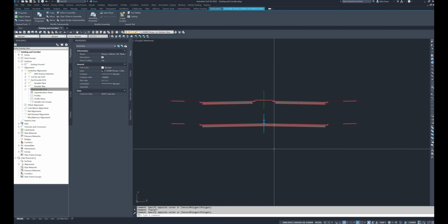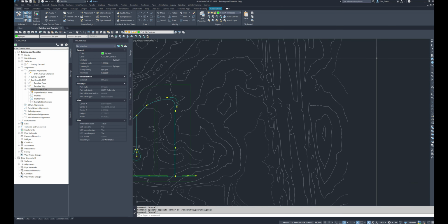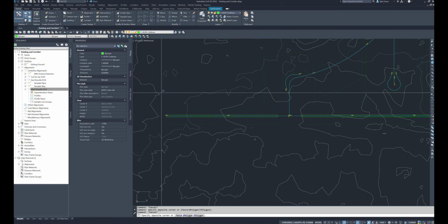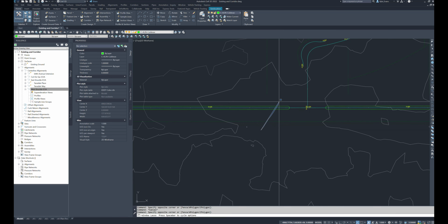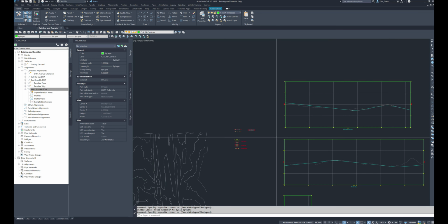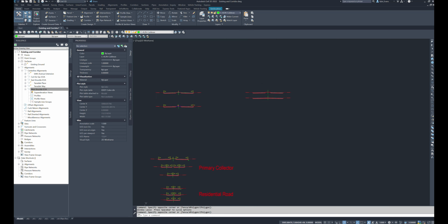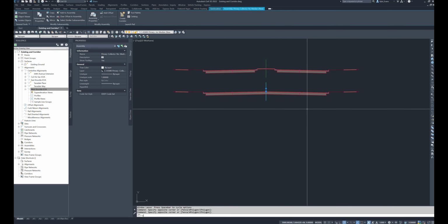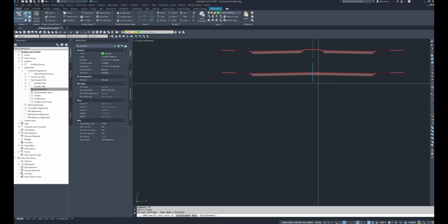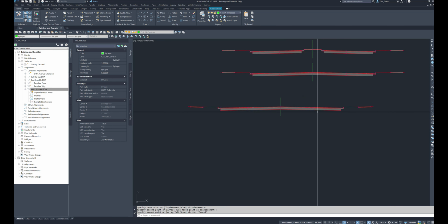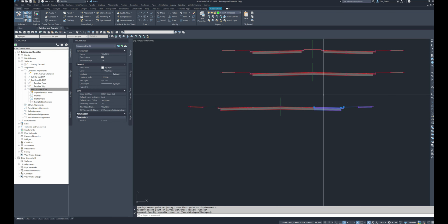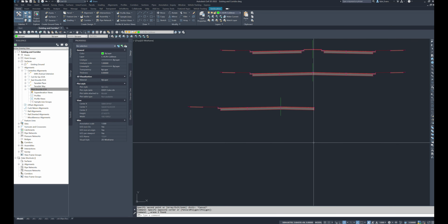Now, this one generally happens before the intersection. So we have our regular assembly, then we have the no median one for a little bit, and then we have the one that's directly connected to the road to the north. So we now need to make 2 more additional assemblies for this. So I'm going to copy this, and I'm going to place it slightly here to the left. And what I'm going to do is delete that.